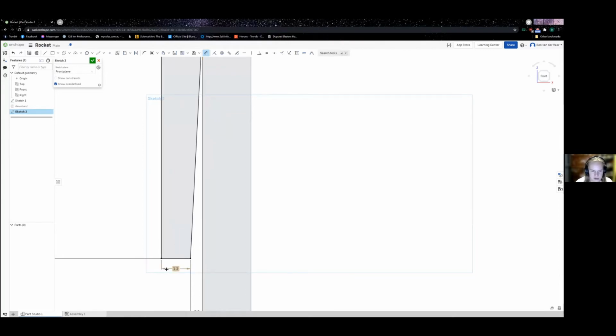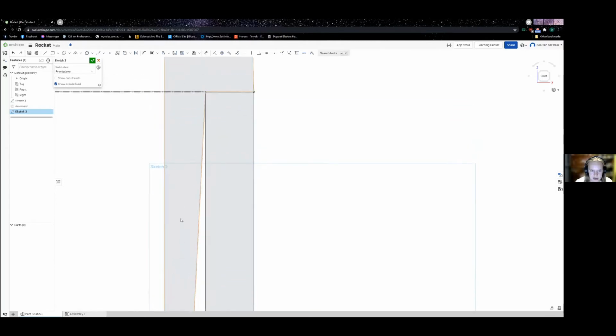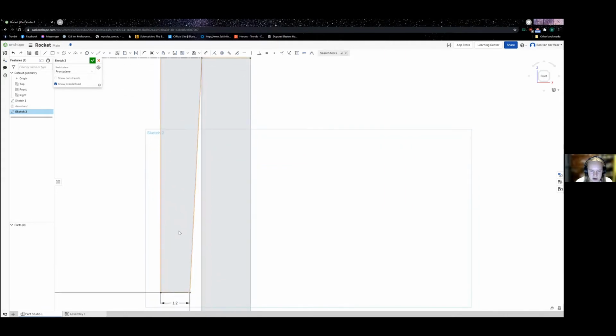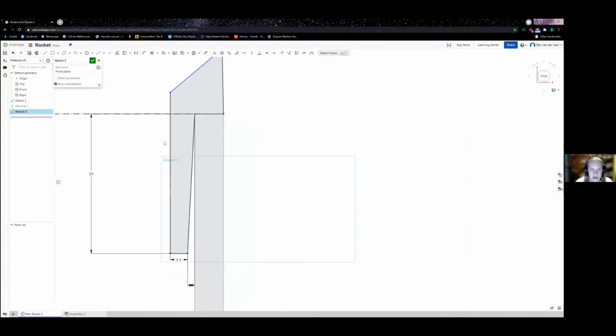We'll work with roughly thinner walls. So 1.2, that's a multiple of 0.4. So we'll have nice three beads of plastic nicely laid down by our 3D printer, and that'll be fine. But as we make our way up, because the thickness is varying, you'll start to get gaps in your 3D print, which weakens the structure. So you don't want one side tapered and one side not tapered.